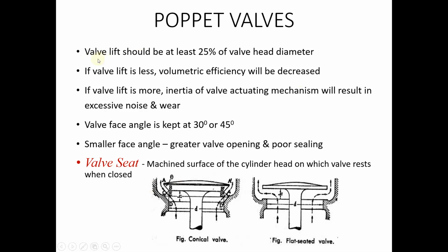The valve lift should be at least 25% of the valve head diameter. So usually that is the ratio that is maintained.